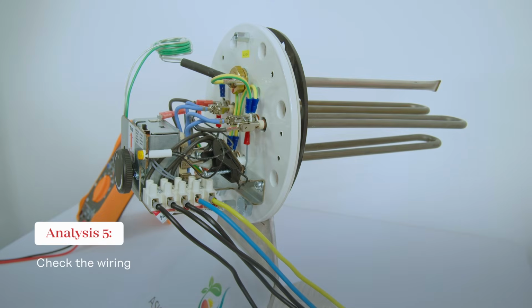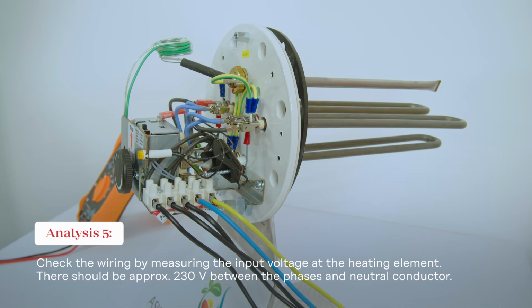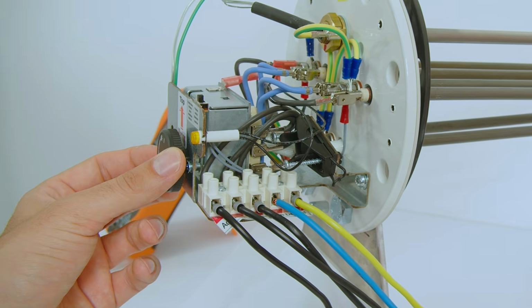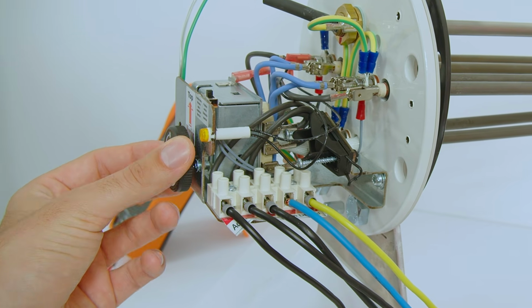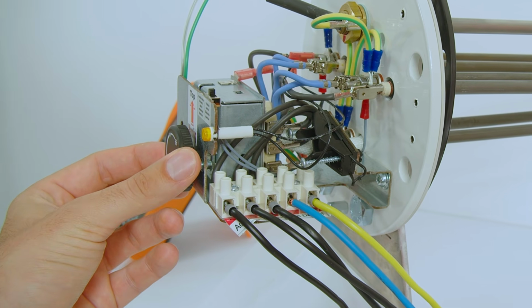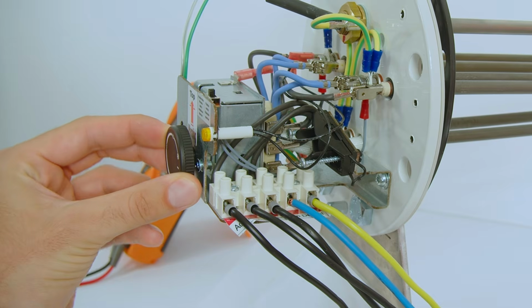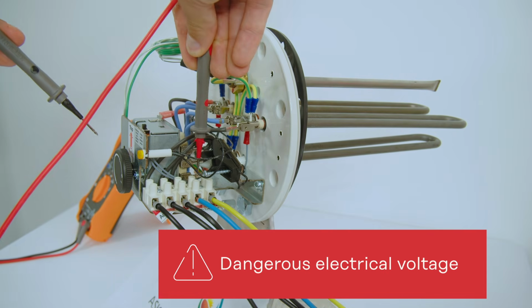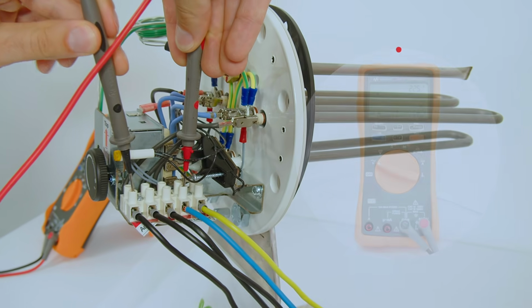In order to check the cabling, we check if the 230 volt output of the Ohmpilot also is received at the heating element. So between each phase and the neutral conductor, there should be 230 volt. Before we're measuring that, we are activating the bimetal limiter. So we are going up with the temperature until we hear the click noise. And then I measure voltage between the neutral conductor and the phases.